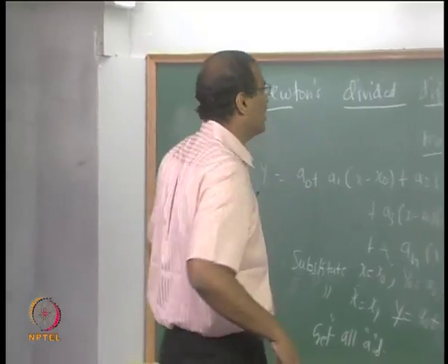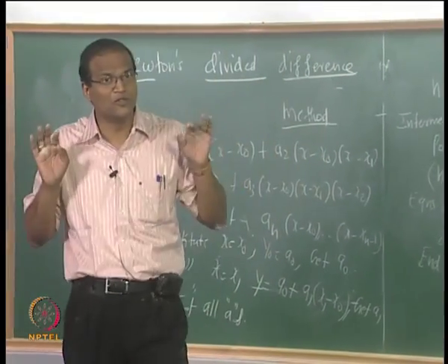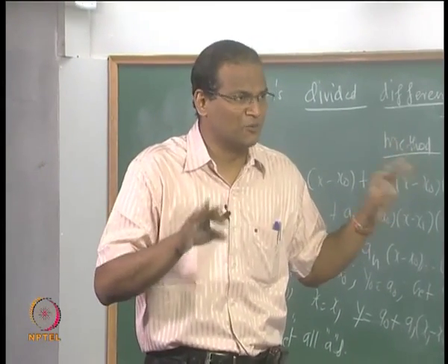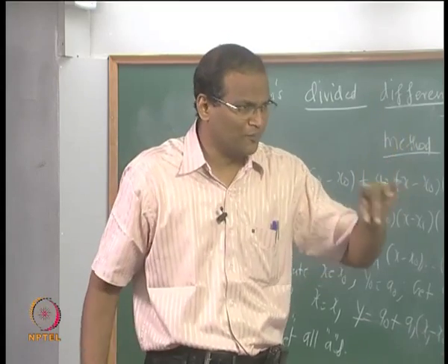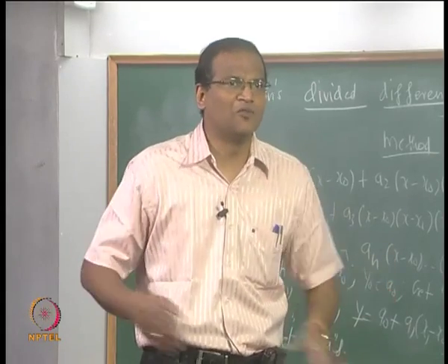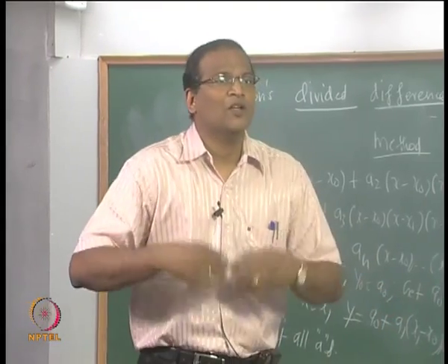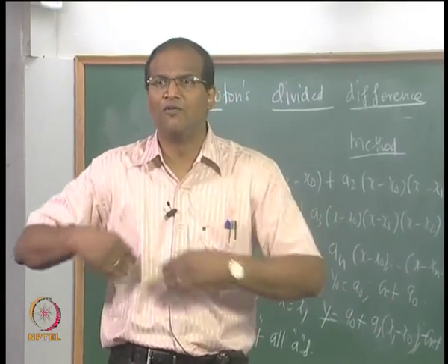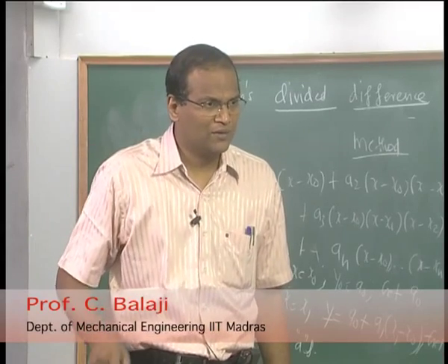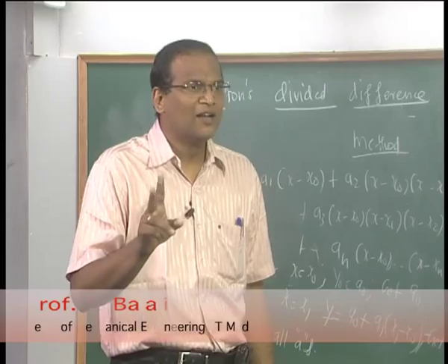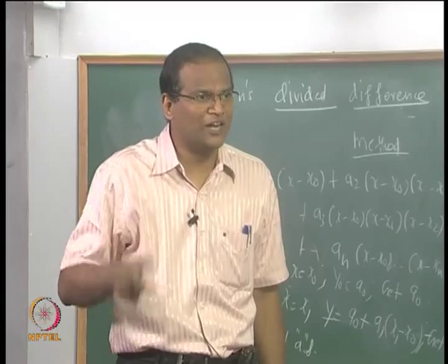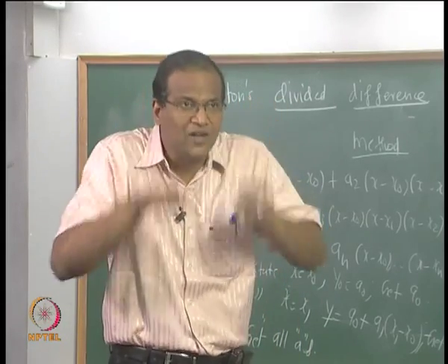So this brings us to the end of our discussion on exact fit. There is so much of story to be told about exact fits itself. These are all properly determined systems where the number of points is equal to the order of the polynomial plus 1. For example, 3 points give a second order polynomial, but oftentimes we have overdetermined systems. You do an experiment for finding the heat transfer coefficient for 10 Reynolds numbers. You know that it is Reynolds number to the power of b into Prandtl number to the power of 1, if Prandtl number is fixed. If you have two constants, two equations are sufficient, but you have 10 or 15 data points. So you try to get the best fit.